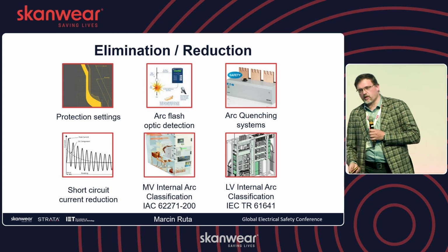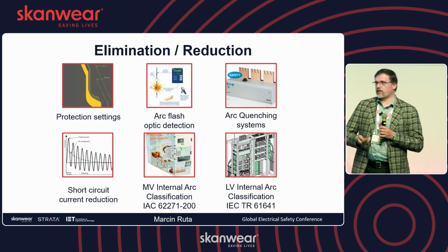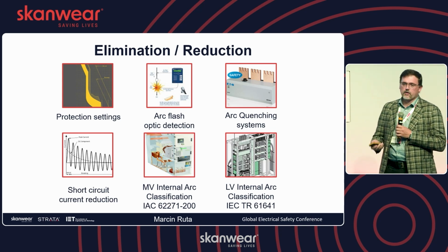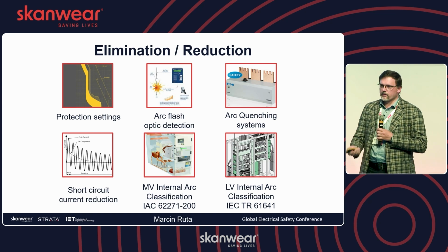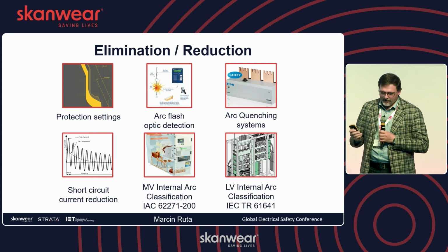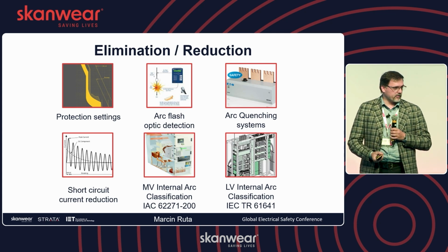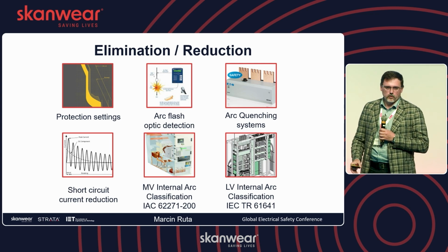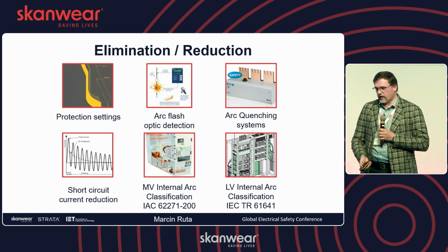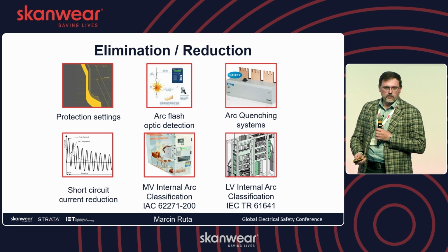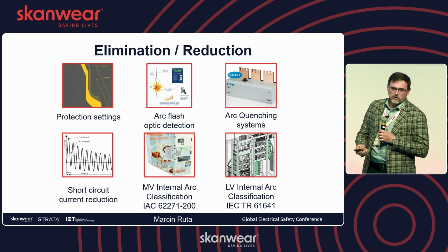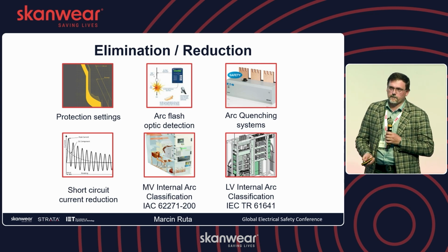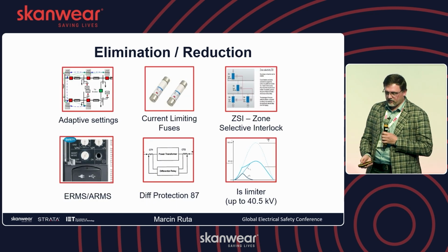But we can also install arc flash relays or arc flash optic detection, depending on what we call it. We also have arc flash quenching systems. It's not new, you will probably hear about it later. Well, we can also play with short circuit current reduction, which is a very tricky topic, to be honest. Of course, design, medium voltage, low voltage. Actually, Sertac will talk about it a bit later. But medium voltage, low voltage arc flash design is a very nice thing to have.